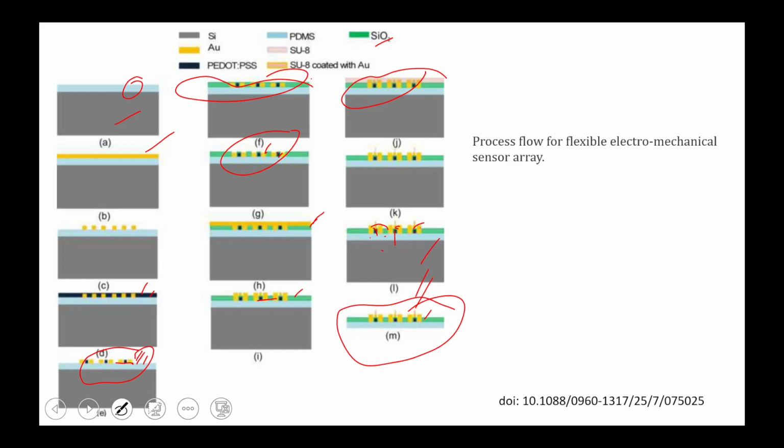And then you use the shadow mask. The IDE pattern I have already prefabricated as a shadow mask. I put my silicon layer on that shadow mask, and then I deposit the gold chrome through that, using thermal evaporation technology. This type of pattern that you see, that gold pattern, will be there as the IDE pattern in the result. So for that characterization, you need the source meters.